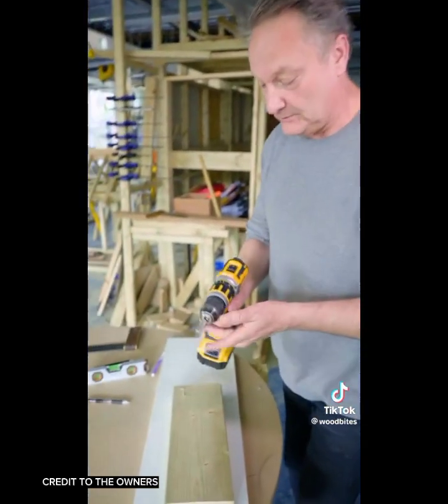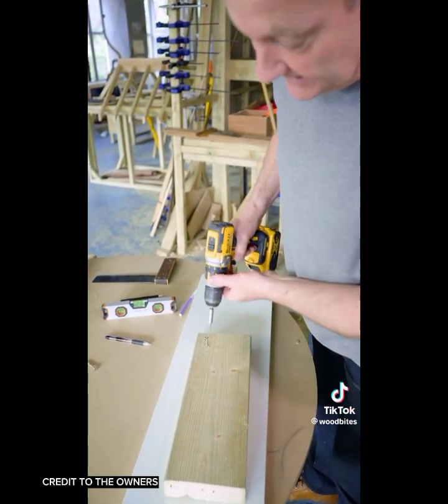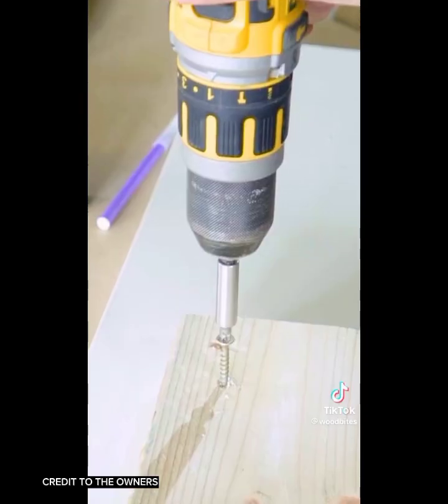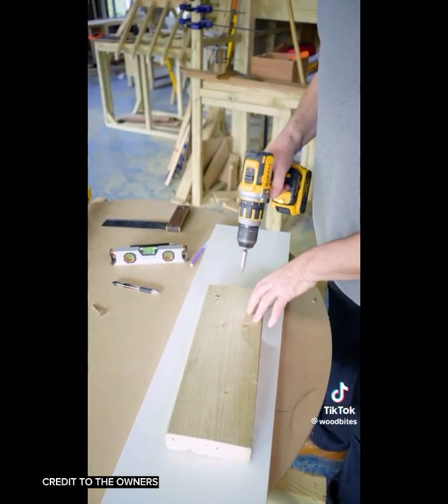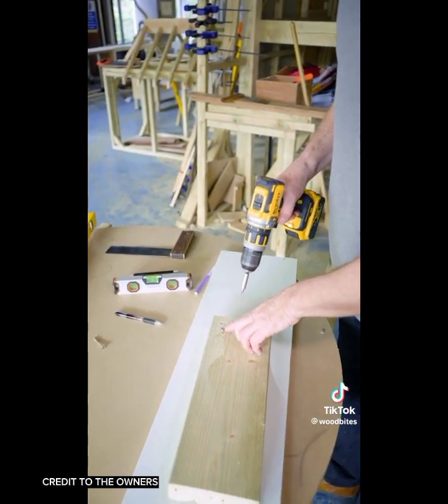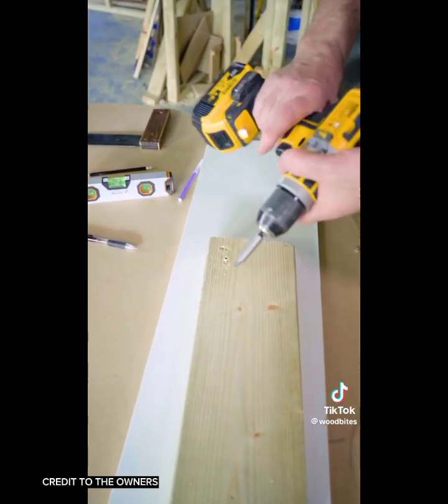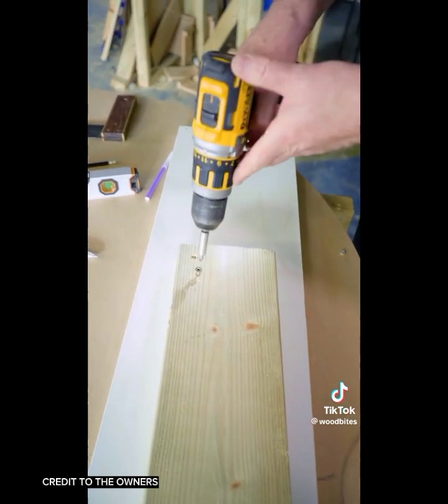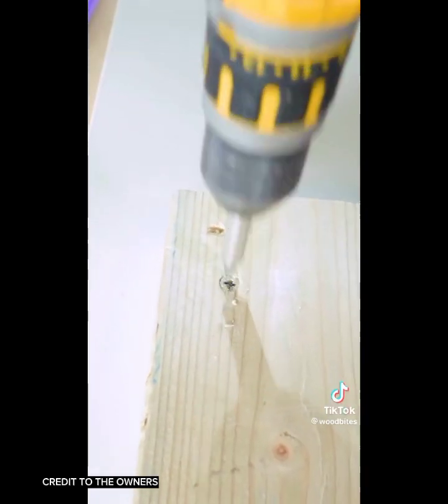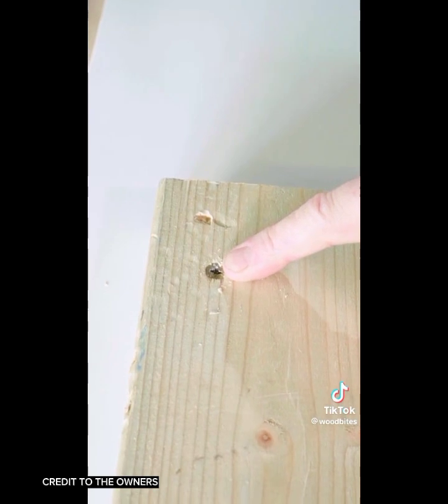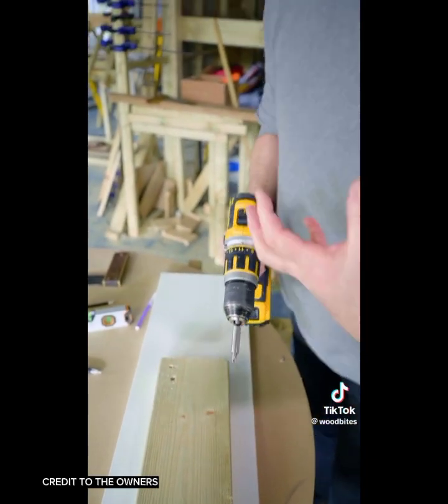Now, the idea of this, it's a clutch. So when you're drilling, as I would explain, if I put it on the lowest setting, this makes a funny noise as you get near the end. Now that stops you going too far. Now I'm going to look at this and I want to take this down a lot further, and that takes it just below the surface. So the idea of the numbers, it acts as a clutch and therefore you don't drive the screws in too far.